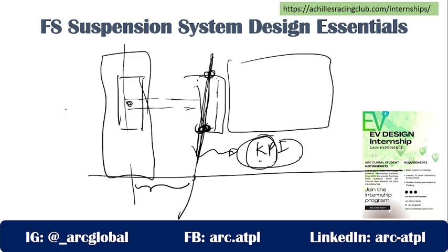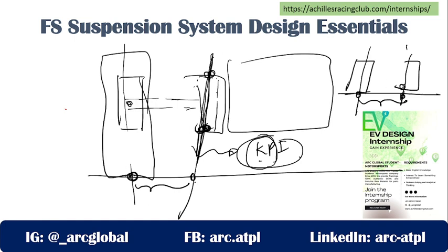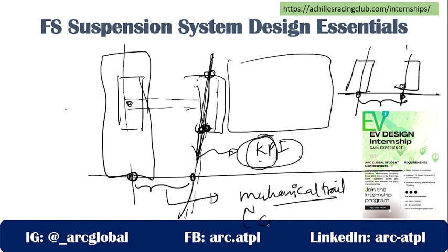So this particular distance here, or if my tire is tilted and this inclination is also tilted, then the distance from the tire center contact patch to this extension on the ground is the mechanical trail, which is the sum of camber trail and KPI trail.